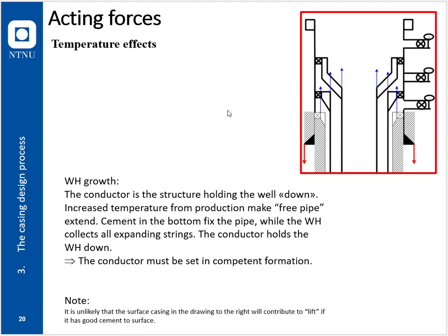because you need to know the different temperatures influencing the different casings, and they are not the same because of all the temperature effects. You have the advection, you have different things, so that the temperature is not the same going out in the different annuli, and you will have different resulting stresses going up.